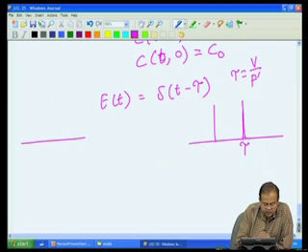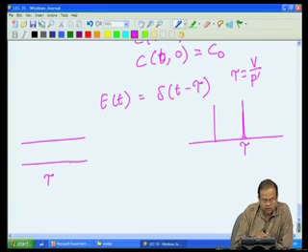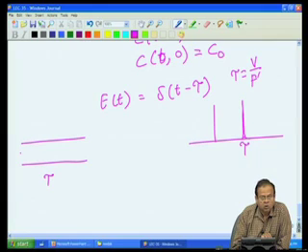So, what we are saying is, if this is the residence time for this reactor, and if we have put in a tracer at t equal to 0 as a pulse input, then we will not see any of the tracer till time t equal to tau.